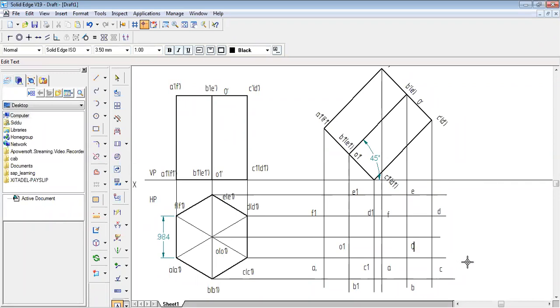Once it is done, we know what the first thumb rule is. I have even told you in my previous classes. Once you locate the points, first and foremost, under the rules of visibility, we will identify all the outermost boundary points and then connect them with a thick line. So which are those? A1, F1, E1, E, D, C, D and B1. These are the outermost boundary points. We will connect them by a thick line under the rules of visibility. In order to do so, we should split it rather than overlapping. We'll do that once for all and then connect it.